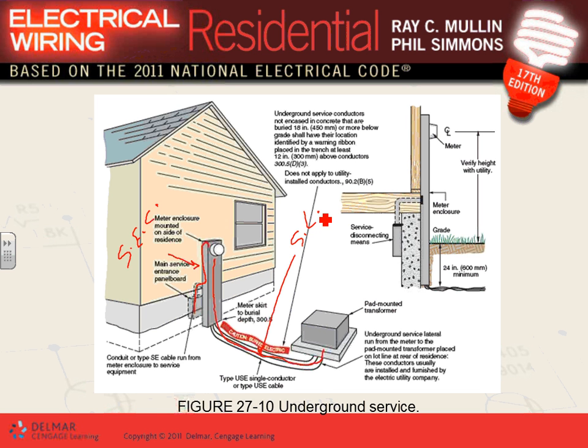So I can't emphasize enough, guys, as we move forward. You have to understand where the service lateral is if we're coming underground, where the service drop is if we're coming overhead, and where the service point is. Because that's going to decide to which point we're going to pull your conductors, as well as your conduits. Okay, so you put them here.